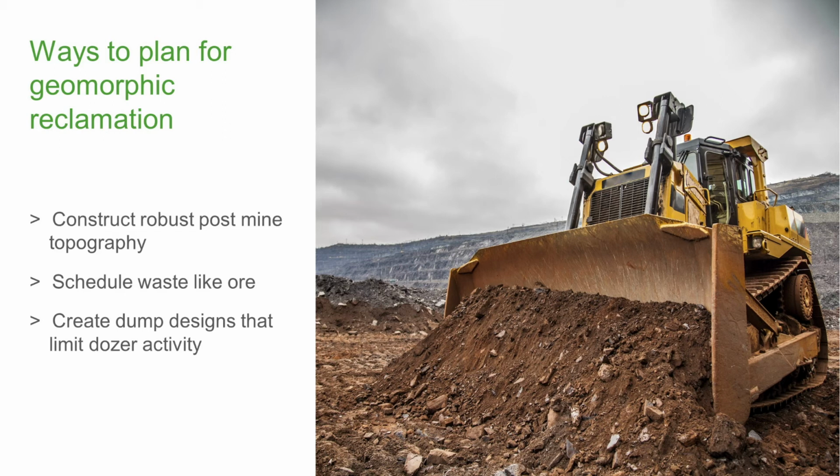This is dumping almost to the final surface, dumping in a way that you are stacking benches and other features to limit the amount of dozer regrade. Oftentimes, the dozer is the tool for final regrade surfaces. And if you can limit as much unnecessary dozer movement, that is the key to creating a cost-effective reclamation plan.